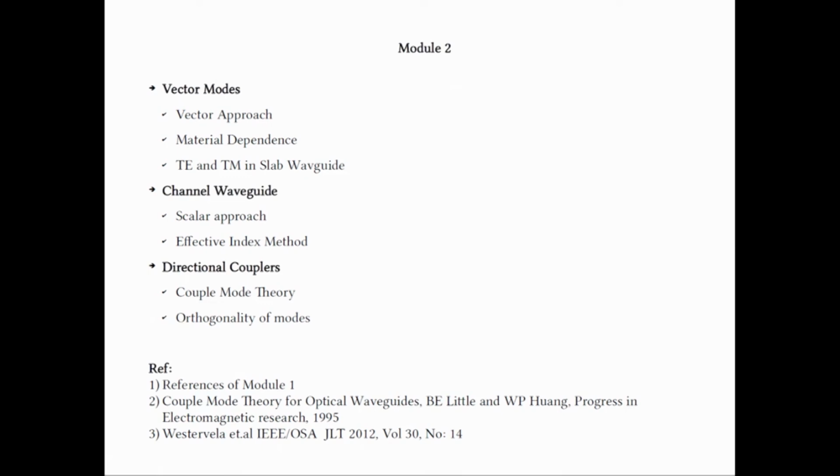So, channel waveguides are now applied to other geometries. One of the important devices we want to make is called the directional coupler. It can be said to be a very general multi-purpose device which can be applied to many applications, like you can make couplers, you can make power dividers, and using other effects like the electro-optic effect, you can make modulators, switches etc. by using directional couplers. One of the most important properties and striking results is that the power launched into one of the waveguides can be exchanged with the other waveguide even though there is a small gap in between the waveguides.